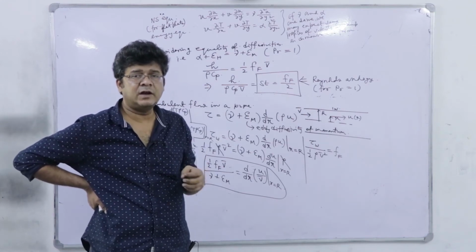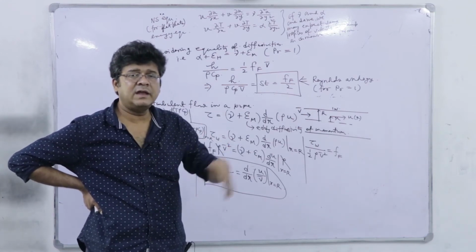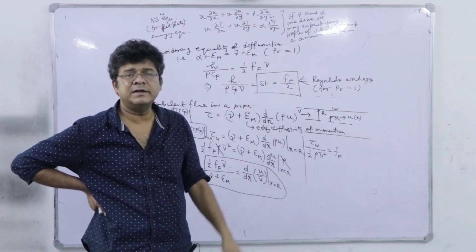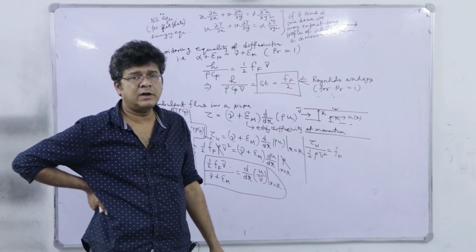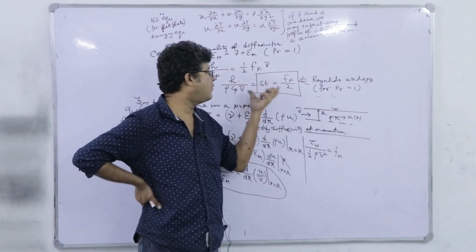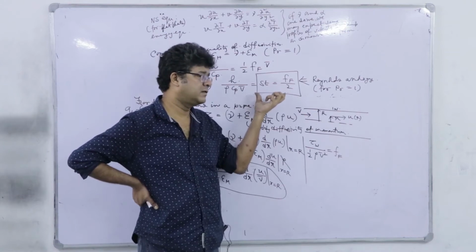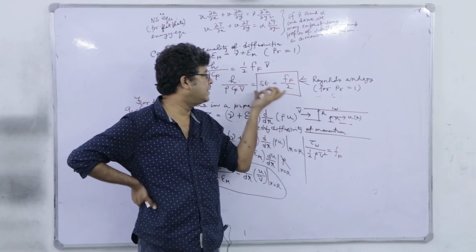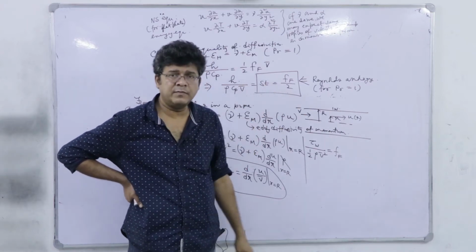Definitely that does not mean we will intentionally go for rough pipes for higher heat transfer coefficient. That is not economically feasible. However, for rough pipe surfaces, with the same thickness of the wall, we expect a higher heat transfer coefficient.